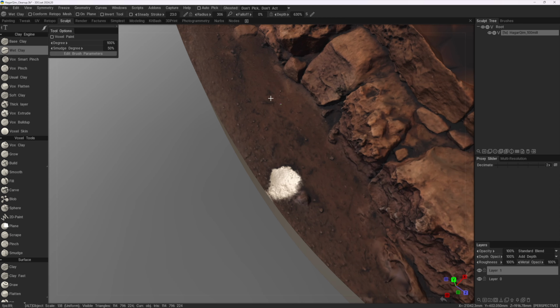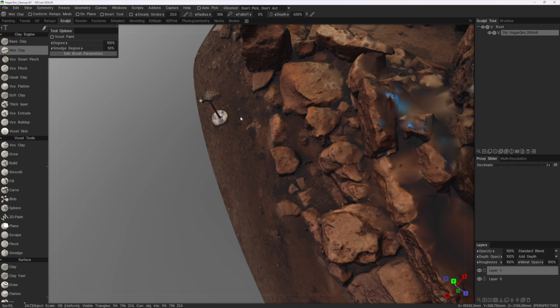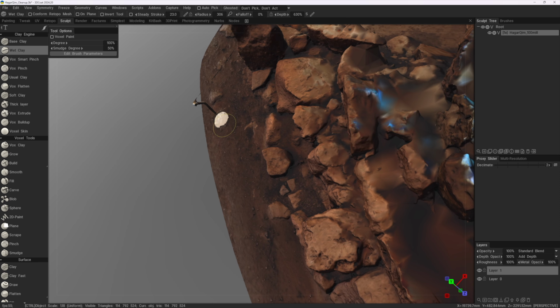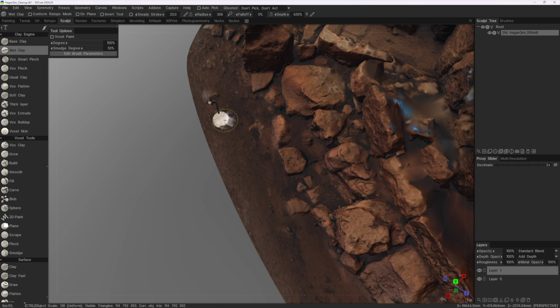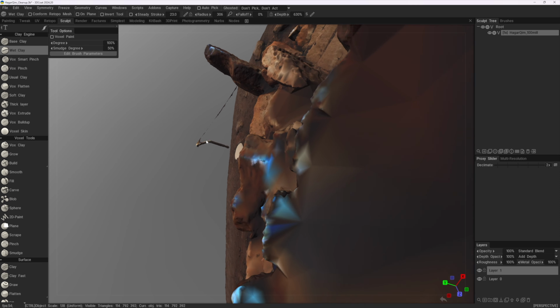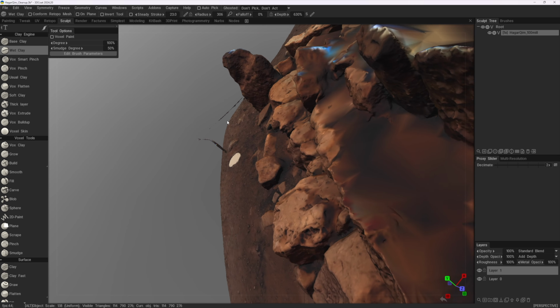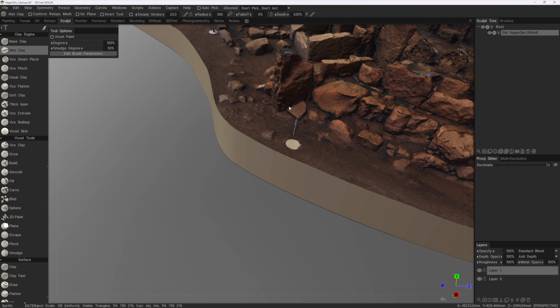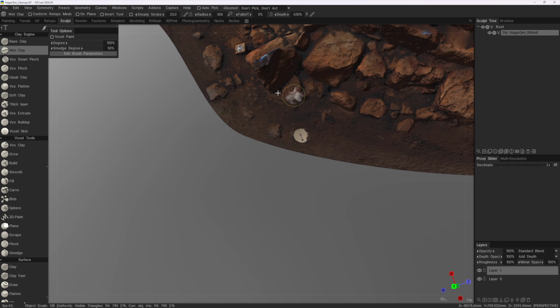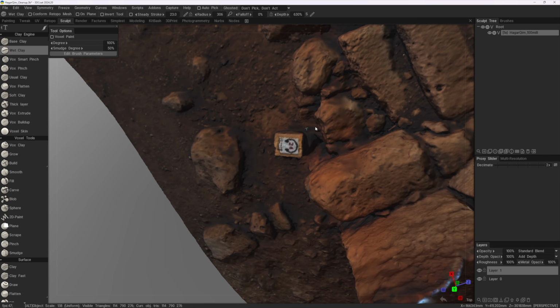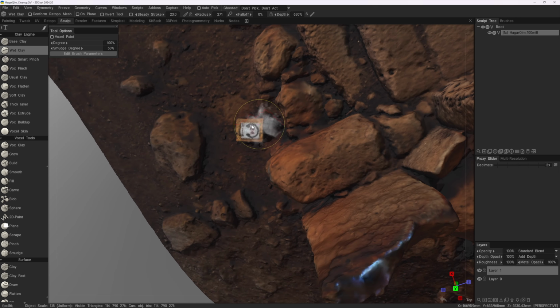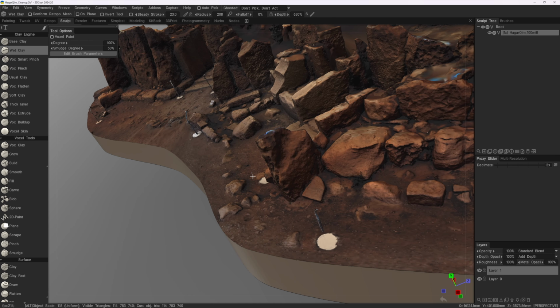And this is why it's good to have the color information already, so that you know where you made your edits. So this we can also use the cutoff tool for, which I probably will do. We are going to convert this to surface in the end and just remove all the floaters, because you can get a few floaters in voxel mode.